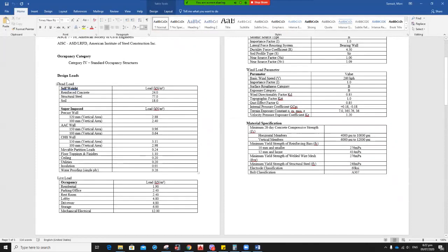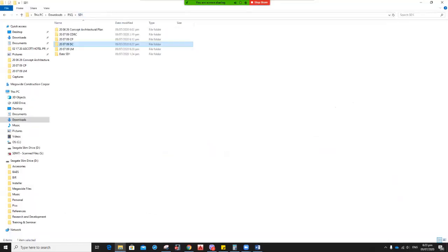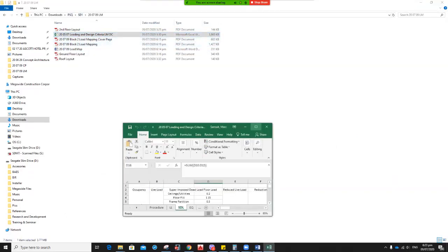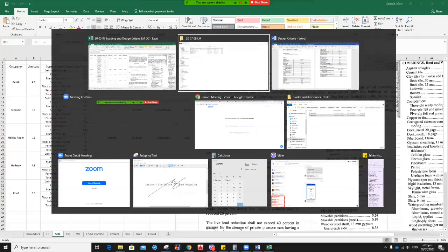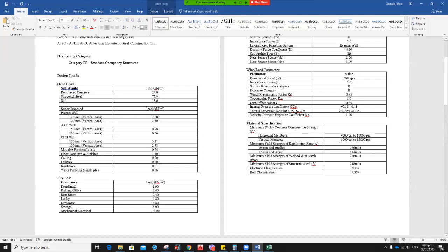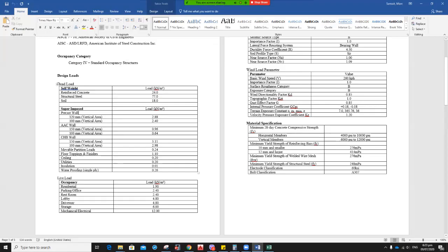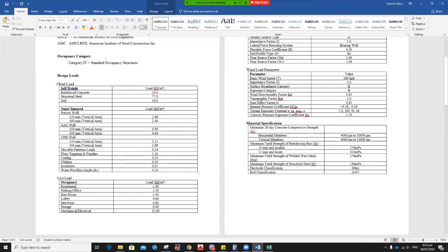And then for the superimposed loads, you need to open the load map of the load reference that you did. The Excel file will be better. Okay. So for the superimposed loads, although we didn't put the drop wall, definitely we will have a drop wall along the way because we don't know the finishes yet of the exterior. So just put the precast wall there. So we have 2.8, 120, 100 mm.